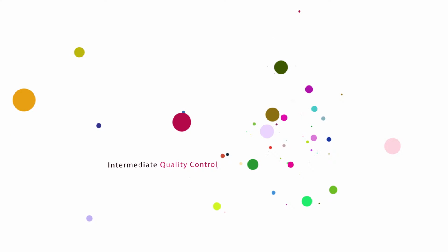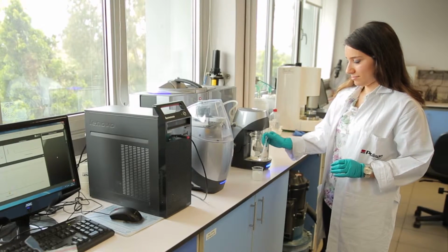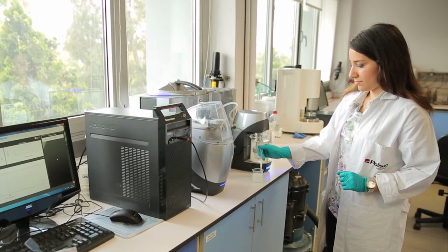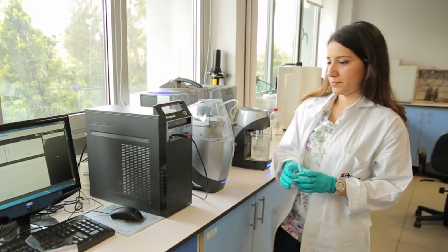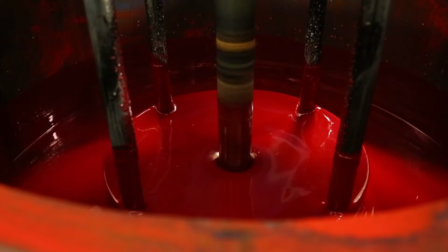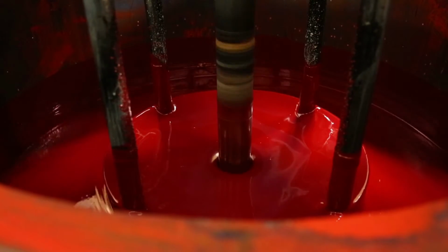Intermediate quality control. Upon achieving the required surface in grinding machines and reaching the required particle volume, it is subjected to the quality control process again. If it is suitable, the production is continued. In some products, where the desired granule size cannot be achieved through dispersion, grinding is made in horizontal or vertical mills which contain balls made of glass, ceramic, zirconium, etc. This process continues until the desired ball size is reached.